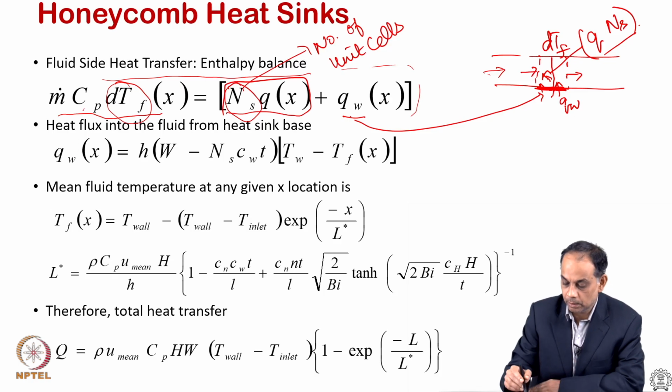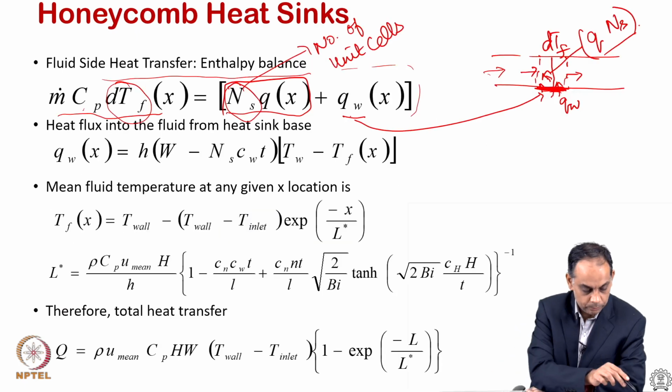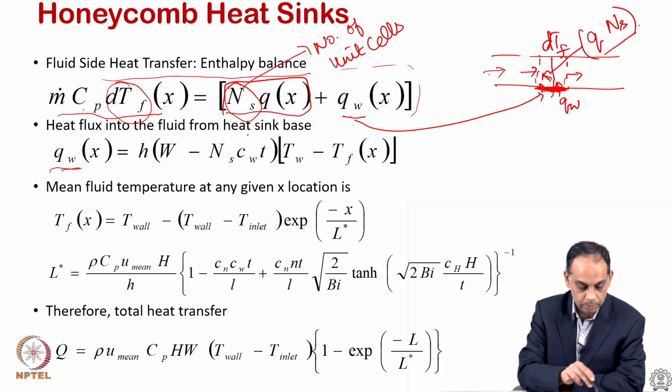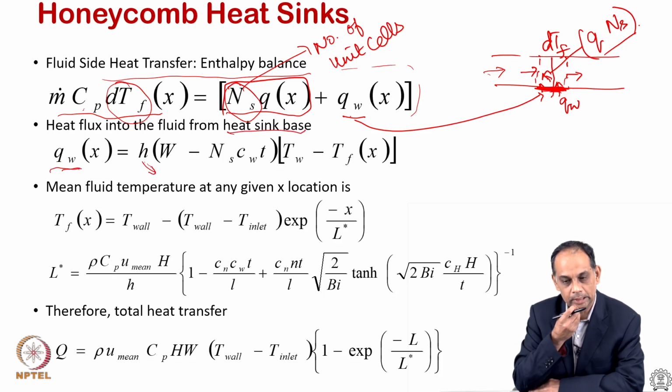So in order to calculate the bottom wall heat transfer, where the fin is not in contact but air is in direct contact with the bottom of the wall, the bottom face, that is this one. This is acknowledged as Q sub W, and this is the wall from the heat sink base. So for that we need to find another heat transfer coefficient, where you can use either a parallel plate or keep using the same local heat transfer as a duct heat transfer coefficient.